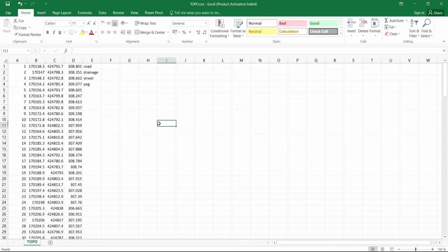So, after that, like I've explained, we have serial number, northing, easting, height, and the descriptions, which is P, that's the point. These are the point numbers. Point P, this is easting, E, N, Z, D. That's P, E, N, Z, D. That is point, easting, northing, height, and description. You can also have P, N, E, Z, D, and this is point, northing, easting, height, and description.